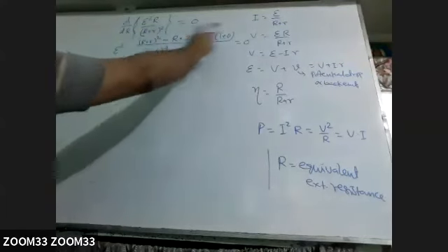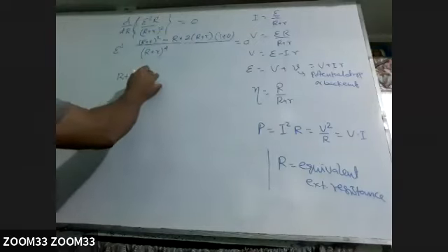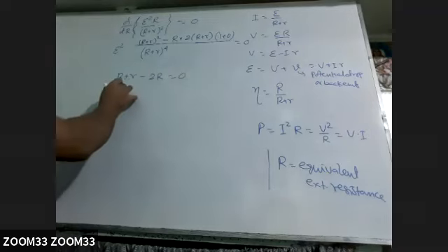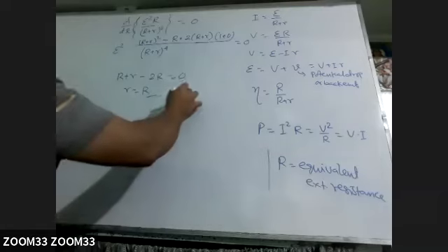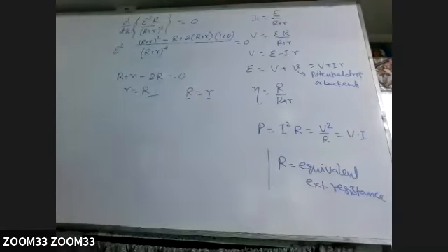So this will go that side, multiplied by 0, E square comes that side. (R plus r) we can take common. So what is left? (R plus r) minus 2R will be 0. That is, this r is equal to R. So when external resistance and internal resistance are both the same, then the source will be able to transfer energy very fast, or at the maximum rate.